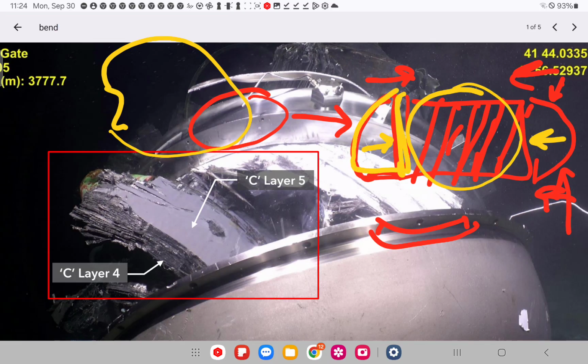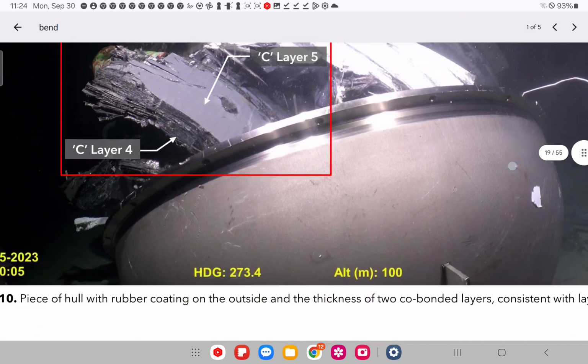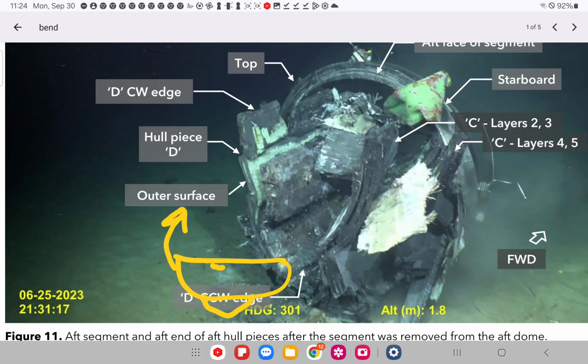oh, I see an imbalance now. Remember, the pressure's all there. It says, oh, you used to have resistance here to stop me, but now it's not there. So that creates the ring wanting to torque in right at that location where it's buckled. The ring pressure on it wants to torque it in, and it rotates. So the back of the head here rotates. Here's the dome with the eyepiece in it. It rotates this way. Looking from the top view down, it's clockwise. It rotates clockwise, and we see this is on an angle into the dome.